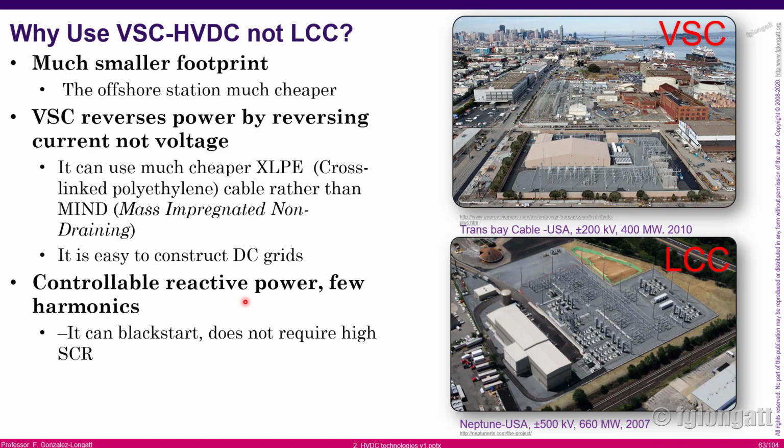Here there are a couple of very good things that we need to know. Voltage source converters tend to be more attractive for offshore wind power. And the reason is you require fewer components, like filters. Filters are heavy. And when you are working in an offshore installation, you need to have a platform. And that platform means a lot of money for each kilogram that you install over there. Voltage source converters don't need filters. As a consequence, they are compact. They have a smaller footprint. That is one of the things that is attractive, okay?